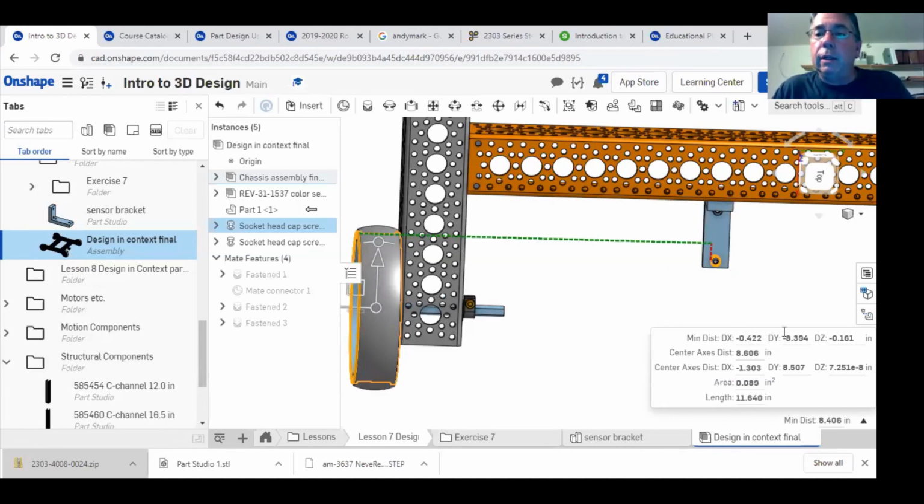And once you highlight these numbers, it gives you a dashed line to try to lead you as to where that dimension is coming from. But you've got to practice, and you've got to check and double check when you use the measurement tool to make sure you're getting really what you want. It can mislead you very quickly.